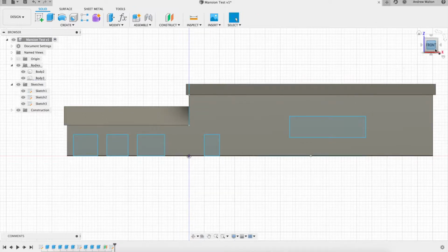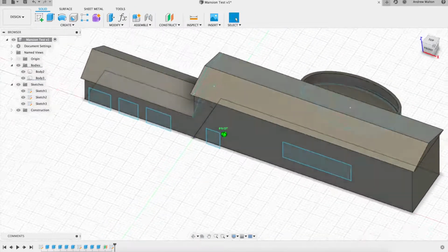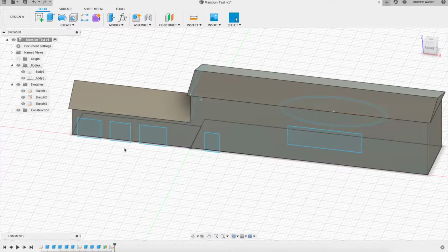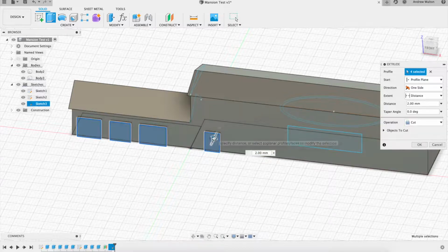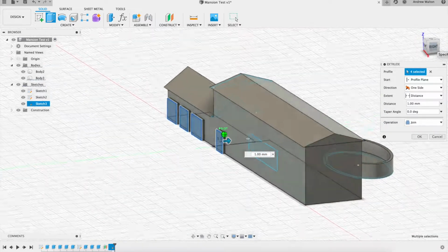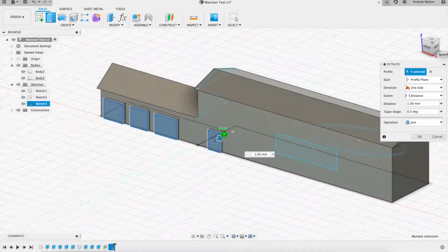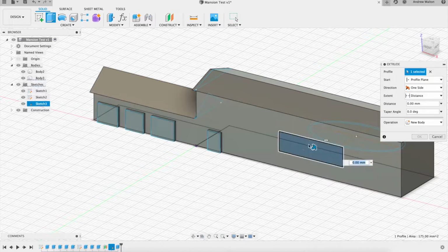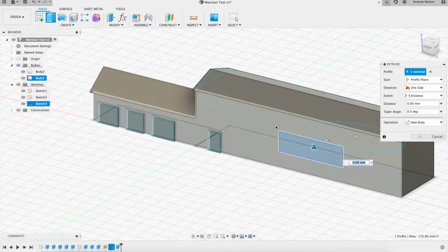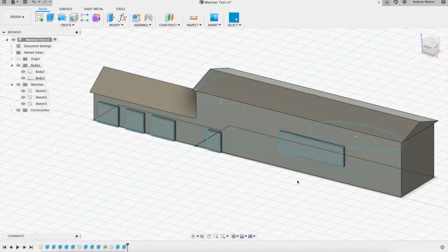Finish sketch. Notice that this is off of the other one by 1 millimeter. So if I grab these ones and extrude them, they would be a solid shape built out from the house, which is okay in our case. Say okay, and I've made sort of a rough shape for the doors on the building. I didn't do one for the windows, so let's go back, turn this sketch number 3 back on, and extrude this to this surface. So okay, that's alright. But what if I wanted these to be door frames instead?